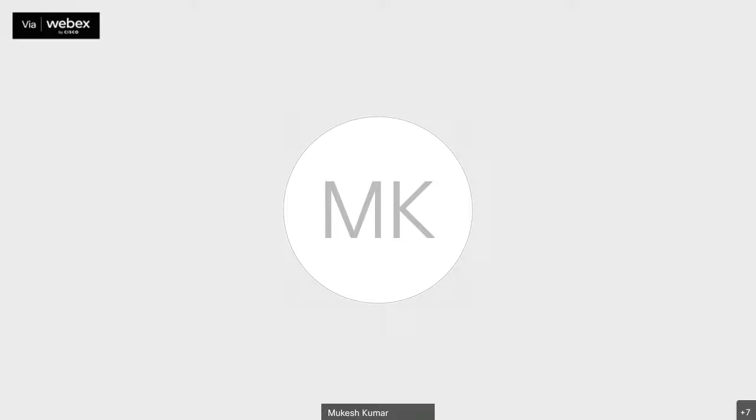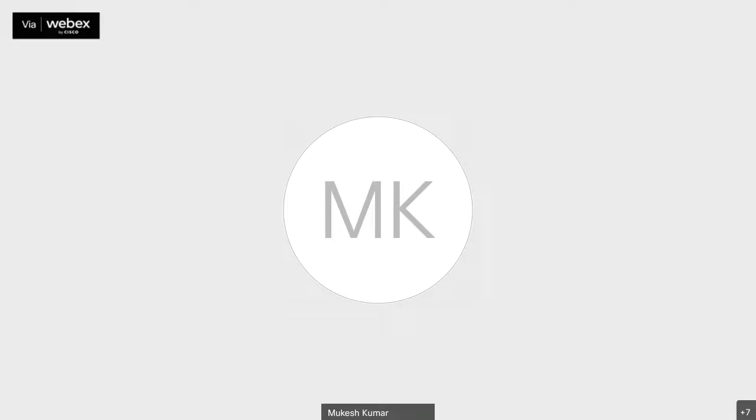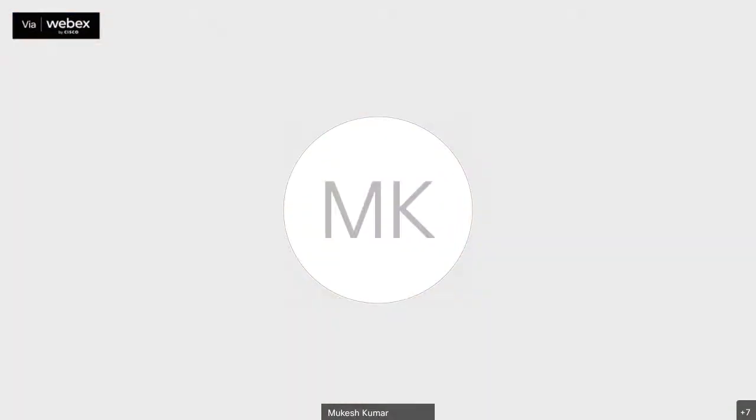Pardon? This stage where you hold the sample, the final device, you deposit at room temperature, correct? Yeah, we deposit at room temperature. But we will increase the heat inside the evaporator. Normally we are not going to see it, but it's going to heat silver. So for heating silver, it's not going to be room temperature? No, the substrate will be at room temperature because the substrate will not be on top of it. The substrate will be here. Yeah, so your deposition material is going to evaporate from here and reach the substrate.